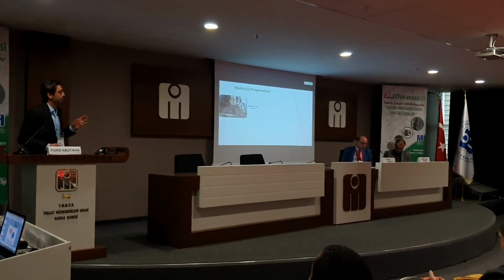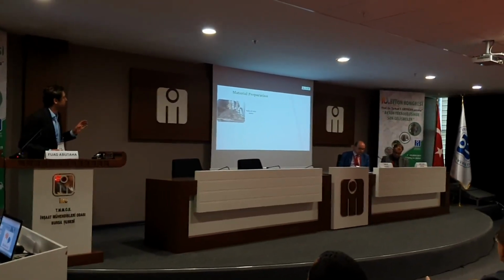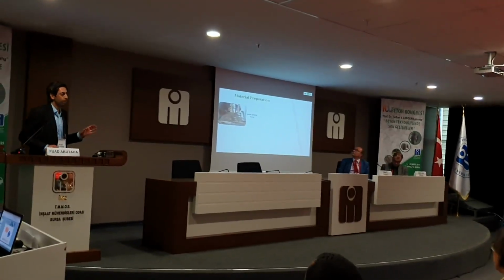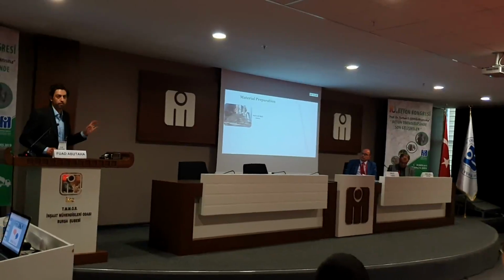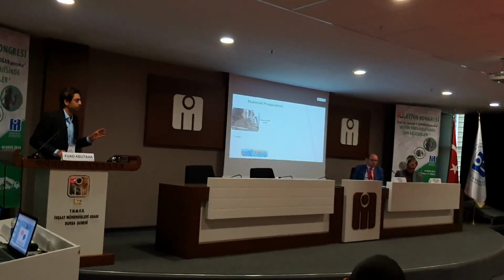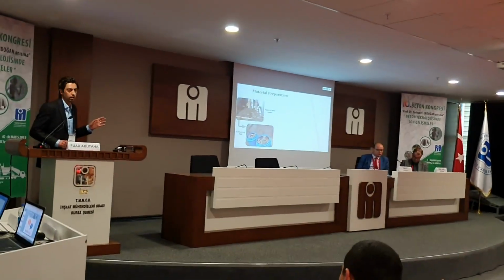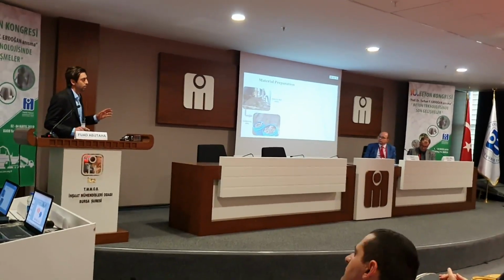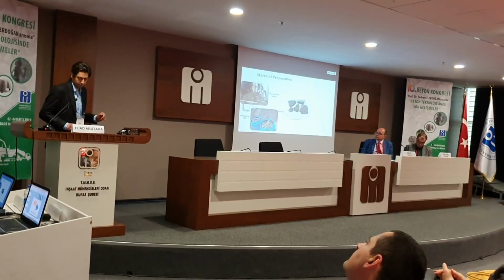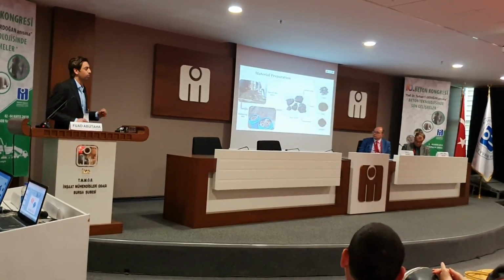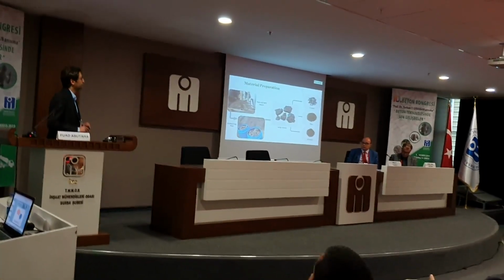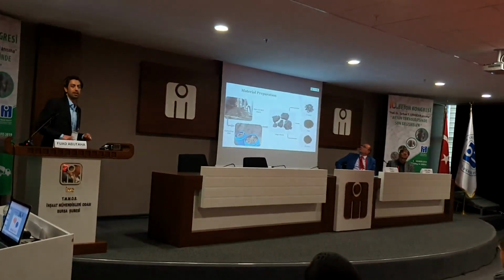For the material preparation, we start from the palm oil mill waste. This is the palm oil mill waste in the palm oil production factory. It was collected in a large drum, and then crushed using a crushing machine and sieved to be used as coarse aggregate and fine aggregate.